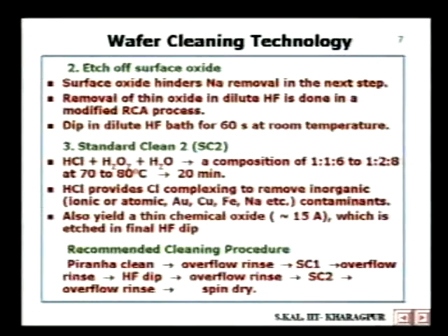After Piranha clean, we rinse the silicon wafer with a step known as overflow rinse. Then comes SC1, which is the ammonia solution, H2O2 and H2O clean. Then overflow rinse. Then HF dip. This HF dip will etch off surface oxide.